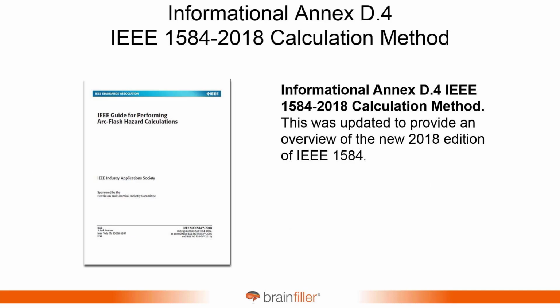One other significant change that I want to discuss is that historically in NFPA 70E Annex D, there have been equations for calculating the incident energy. IEEE 1584, traditionally, the equations have been listed in Annex D. Those were removed. I had a lot to do with this. The reason they were removed is the equations for the 2018 edition are really complicated. There are tables of all these different K values, up to 13 different K values, and big tables. It's a very complex calculation method now.